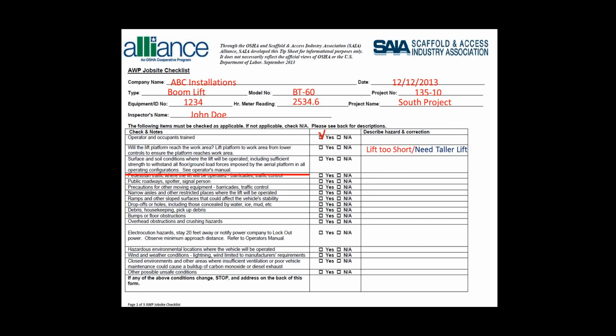There are also different classifications of soil that we need to take into consideration because we may need to put additional outrigger mats underneath the machine to divide the concentrated pressure over a larger area, depending on the best case, worst case concentrated pressure and the soil that the machine's on. Let's say on our virtual job site that we're okay, so I'm going to put a non-applicable there.